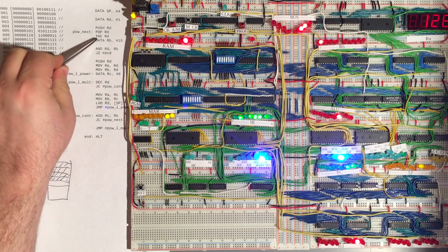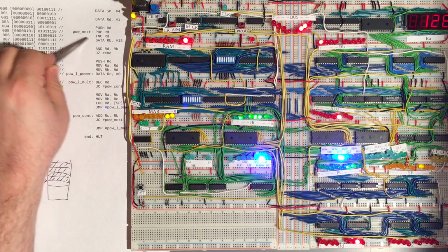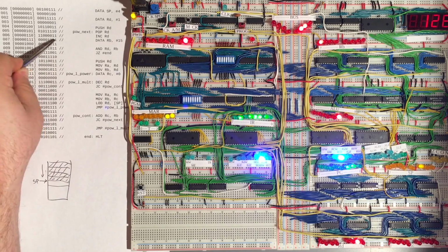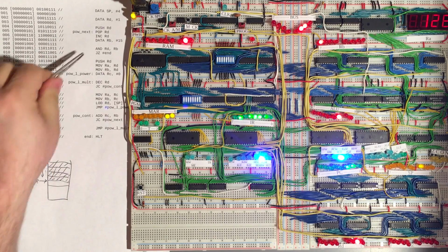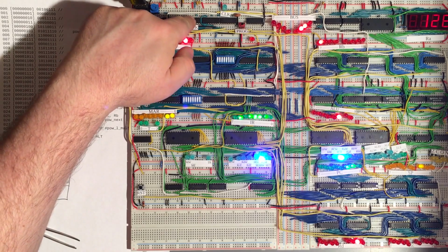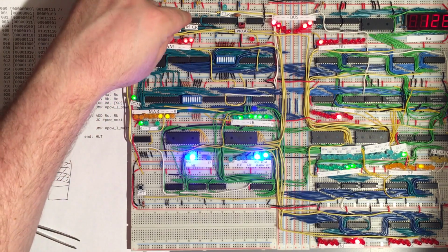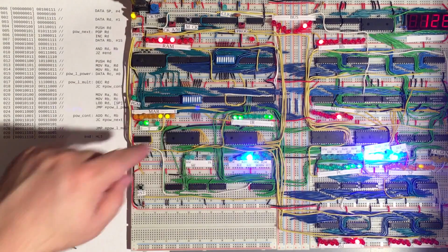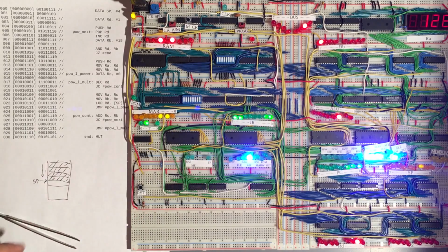And so that next instruction is an increase, which we've already looked at once before, and we just looked at the microcode for that instruction. So that is a simple ALU operation. So beginning always the same. Let's go and fetch the instruction. So address in the memory address register, and then the contents of program memory into the instruction register. And there's our increase instruction.